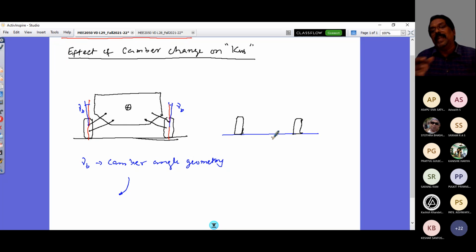this way. So it is lean on the other side like this, and your roll center would be somewhere here, and that roll of your vehicle body would take place. So this is your ground, and say somewhere here is the roll center, this is RC, and this is the CG location of your vehicle. So this body rolls about this roll center. When I take a turn like that, this would roll on this side like that. So the roll effect would be something seen like this.